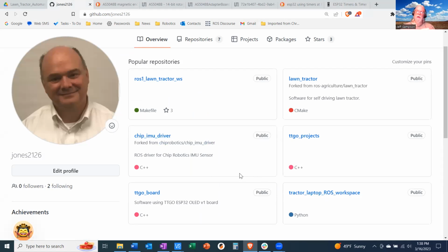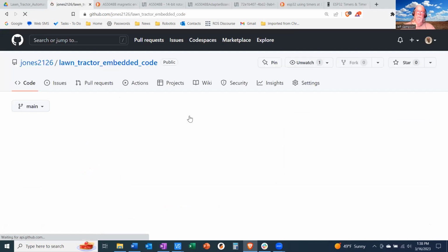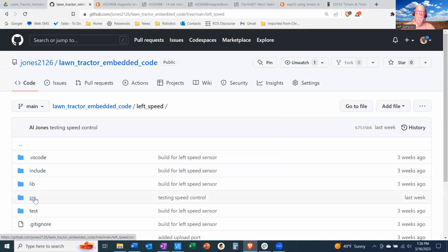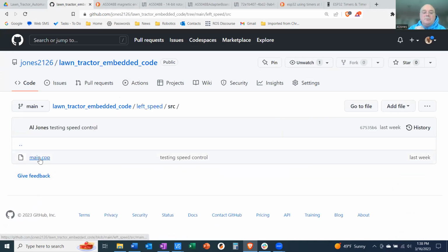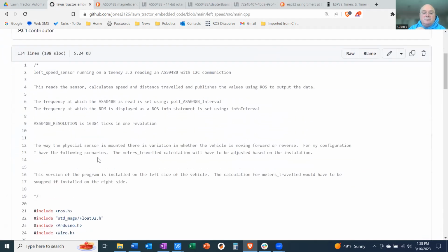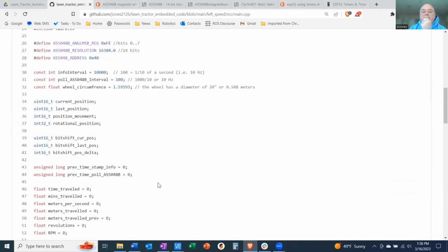It's connected to an Arduino-based Teensy 3.2 board. It's simply a magnet you glue on something, and you put this thing over the top of it, and just by reading the magnetic field, it tells you what angle the thing is. And he's not using it on a motor, he's using it on steering or something. Yeah, this is on the rear wheel. Both rear wheels have one encoder each, spitting out, using this program, the speed and meters traveled.